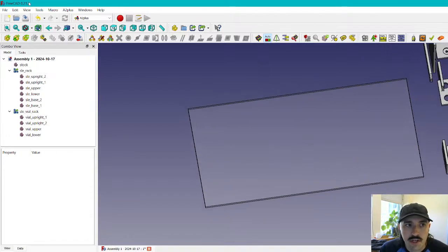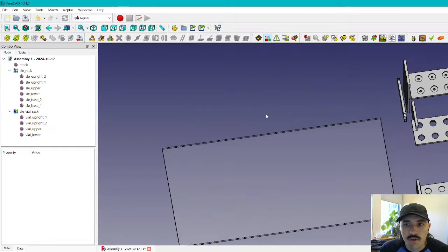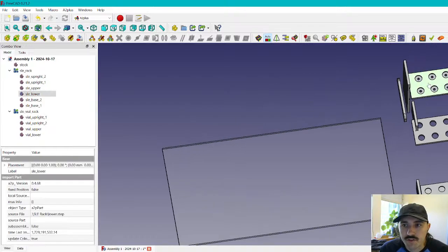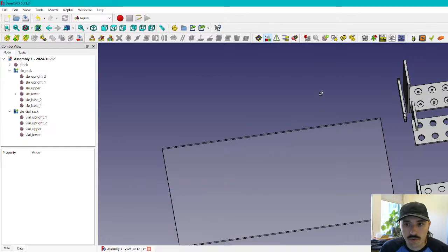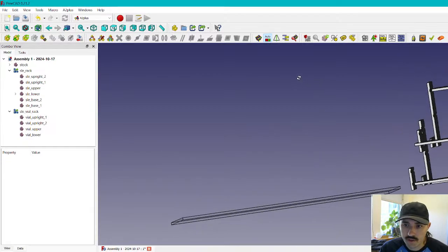So that's a ton of parts. Now we're actually going to start using A2+. So let's go ahead and click the surface and the surface and add plane coincident constraint, which will cause those two planes to now be, well, both parallel and on the same line, coincident. We'll hit accept. So now we can see that moved that surface all the way down.